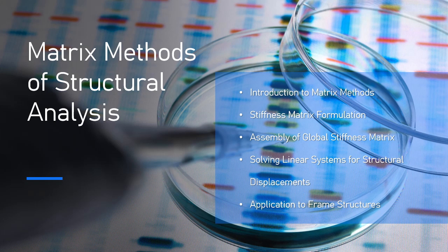A is the cross-sectional area of the element. L is the length of the truss element. This matrix represents the force-displacement relationship for the truss element. For a truss element in a 2D coordinate system, the stiffness matrix is modified to account for the angle between the truss element and the coordinate axis.